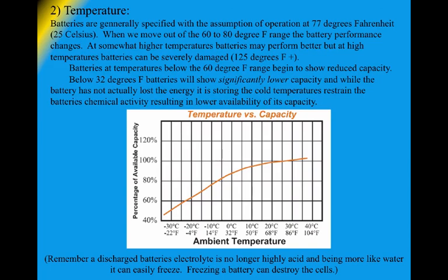Here we have a chart indicating how much, as batteries go below the standard test condition temperature, their available capacity is reduced. And we see that as you get to, say, 10 or 20 below Fahrenheit, we've really lost as much as half of the battery capacity. Now remember,